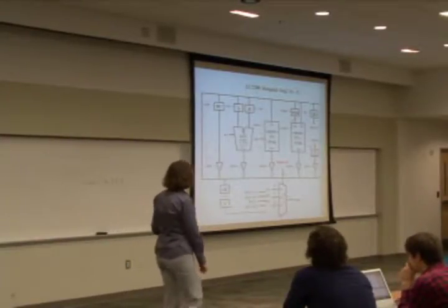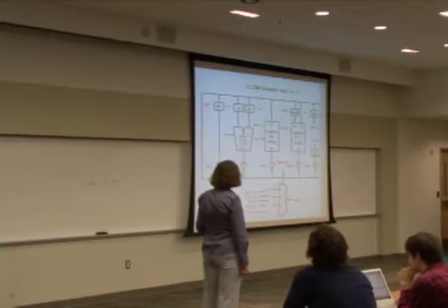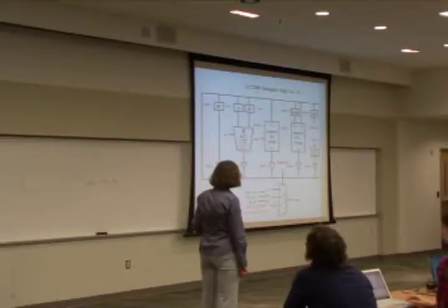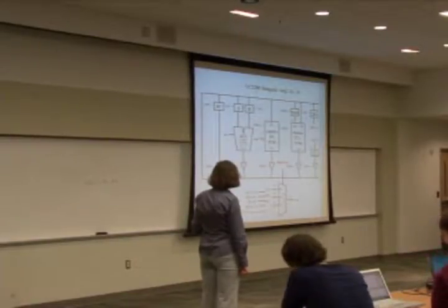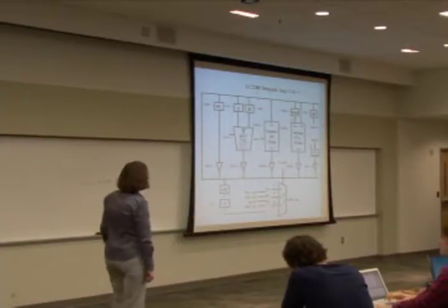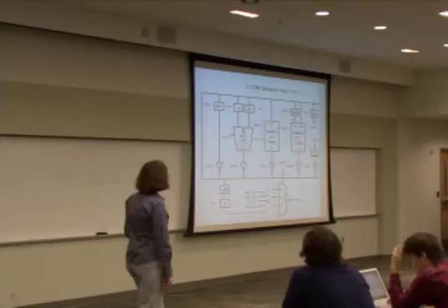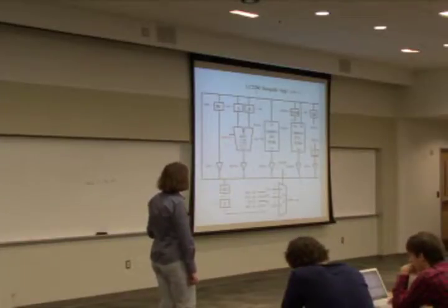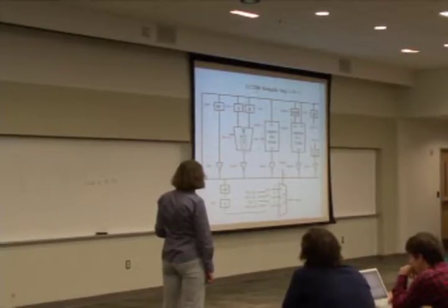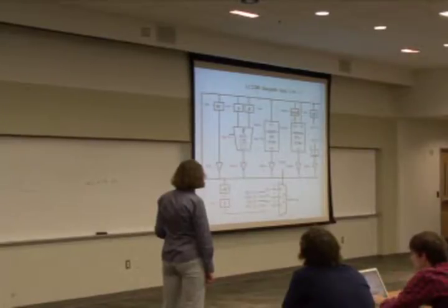What do we do next? We take Ry and store into B. So again, the same steps. The only difference is the register selector is now 0, 1. And that gives you the new address. And you write that on the bus and load it into B. So now we do the following. We subtract A minus B. And we do that by setting function to 1, 0. So A minus B is performed. And that result now has to be written into Z.